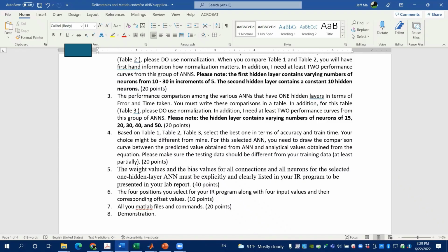To compensate for the pushing back of the industrial robot's hand from the workpiece, we can give the hand a little bit of offset. The value of this offset depends on how the hand interacts with the workpiece.